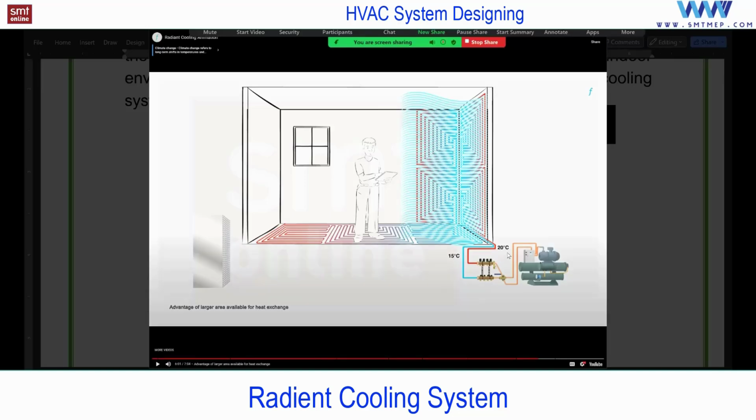One more point here, you see, the delta T is not much in this compared with the chillers. You see 20 degrees centigrade, 15 degrees, 5 degree is the difference, delta T. Sufficient cooling can be achieved with higher chiller operating temperatures, which in turn results in a higher coefficient of performance for the chiller and consequently lesser energy consumption.